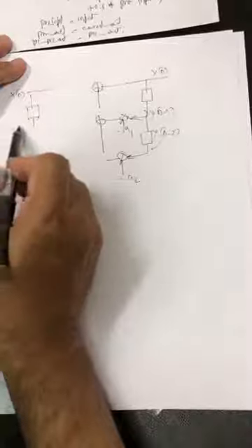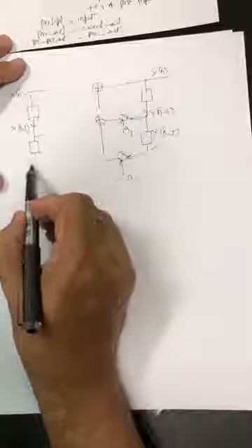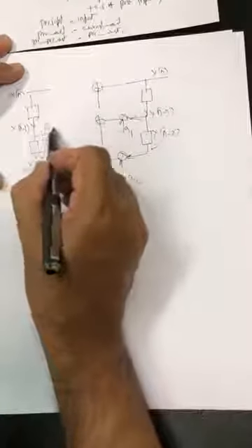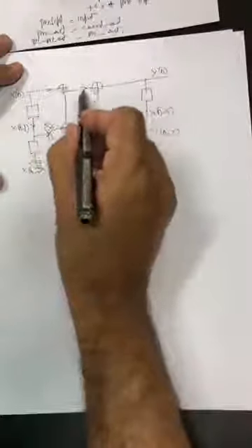Okay, and then you have this x of n, you put a delay here, so you get here x of n minus 1, you have another delay here, or a variable storage, here you have x of n minus 2. So you do a multiply here, which is b of 1, you have a multiply here, which is b of 2, you add, and you add. And you can directly convert this, if you have an FPGA, so you use 1, 2, 3, 4 multipliers and 1, 2, 3, 4 adders to implement this.